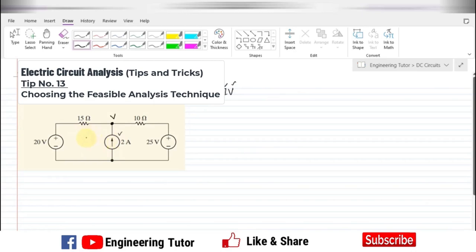If we solve this circuit by using the mesh current method, we can see here that we will have two meshes. The first one will be here, the second one will be here. We have to consider the currents 1 and 2 here in any direction. Let me consider them in the clockwise direction, like this one.